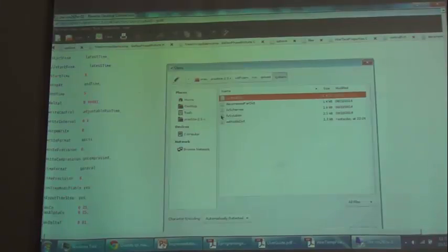How are those Courant numbers forced? So basically, here we are adopting something called a variable time step, as you do in Fluent, right? So it basically varies the time step. It checks the global Courant number. It accesses a header file called CourantNo.h or something. So it basically returns the maximum and mean Courant numbers.